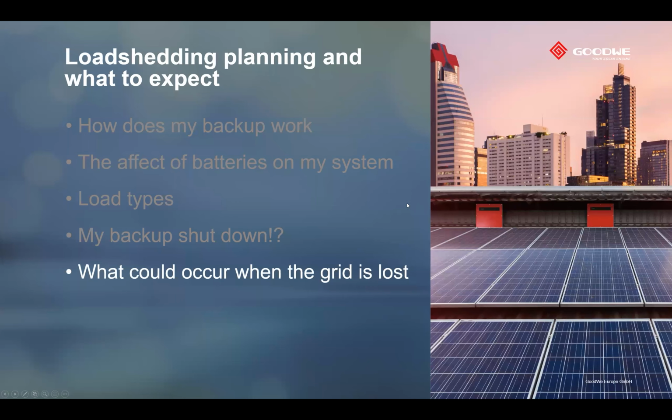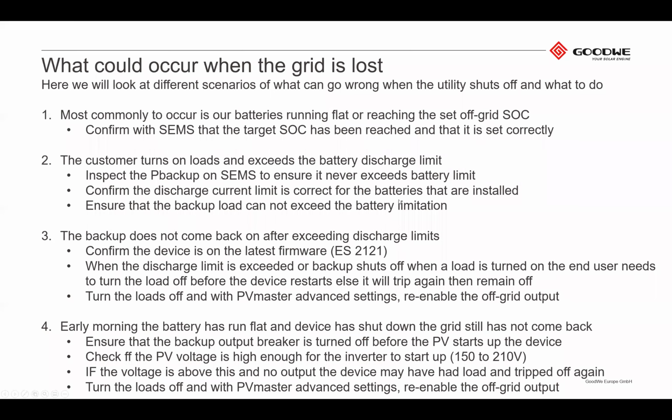So then next is just a list of things which, in my experience, have occurred previously when we have outages. Very often it is installation-related things that occur, especially, like I said earlier, you install the system and there's no load shedding for 3 months. So we see a working system, there's no issues. And 3 months later, we had installations for over 3 months happening. So hundreds of inverters being installed and never really stood the test of a load shedding happening.